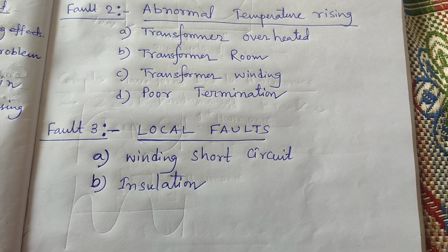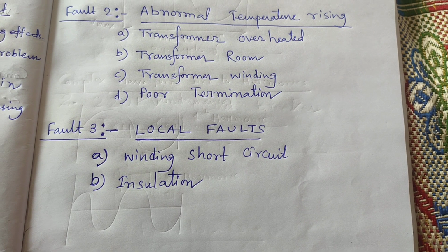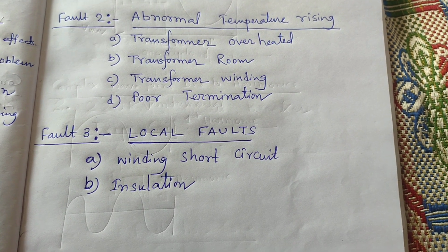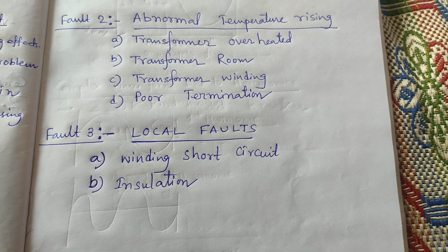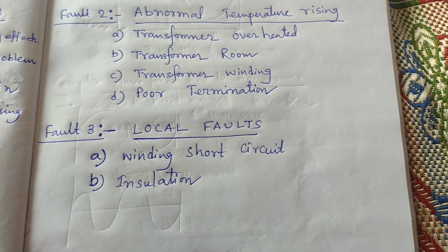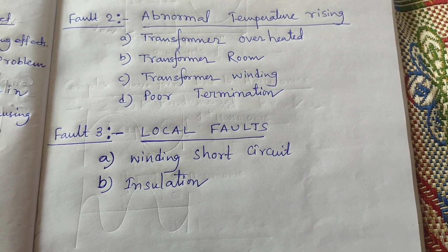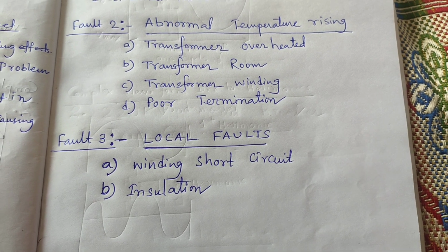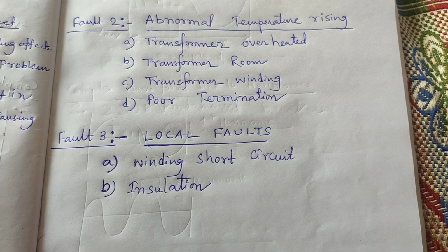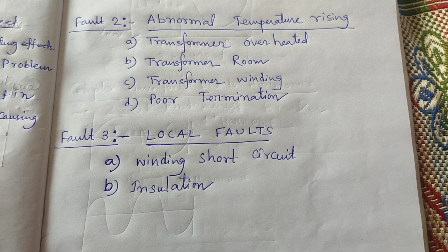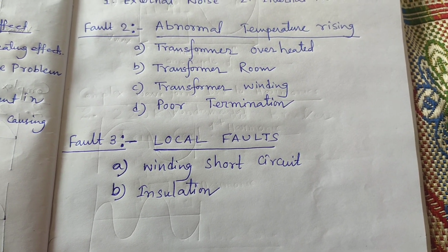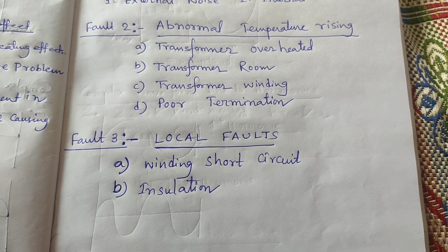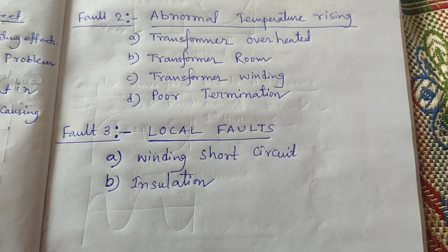We should check whether some wiring or electrical fault is there, thoroughly checking all the connection points of the MCBs, all the MCCBs, all the relays, all the contactors, and all the wires. If some problem is there, we should check and properly replace the item quickly.